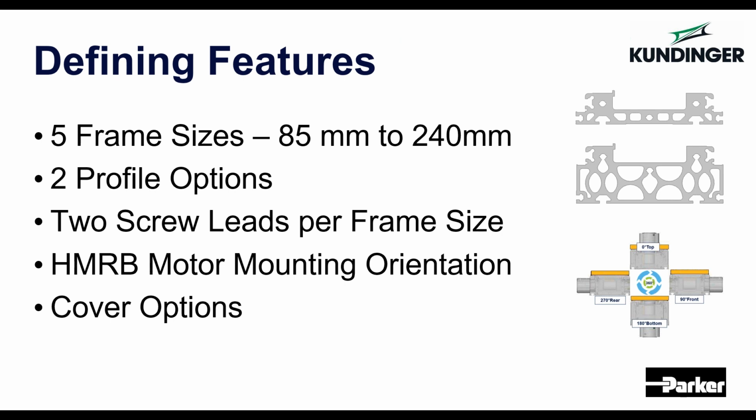You can move it down to the complete other end of the actuator if you so choose. The reason we're able to do that is because the HMRB actually tensions the belt at the carriage. Another advantage there is you can actually change your belt should you need to, or adjust your tension without having to remove your payload, meaning you're able to minimize your downtime quite a bit.